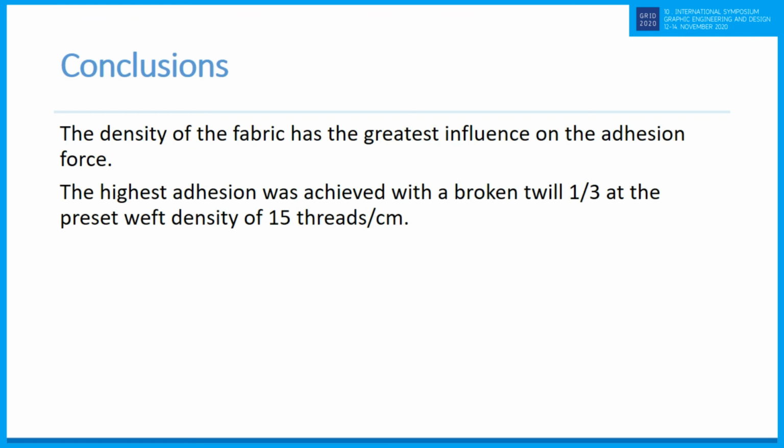Results show that the adhesion force increases with increasing thickness. The fabric thickness, measured according to the textile standard, generally increases with decreasing weft density, which leads to longer floats on the warp threads and to larger available yarn surface for polymer adhesion.